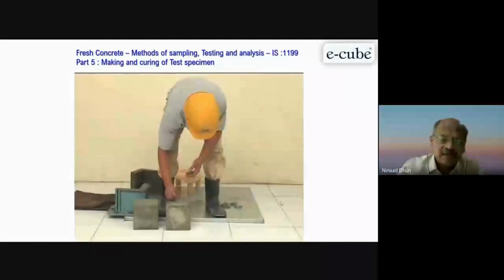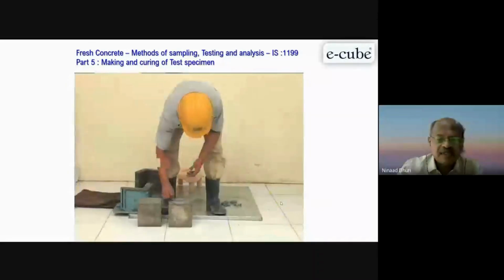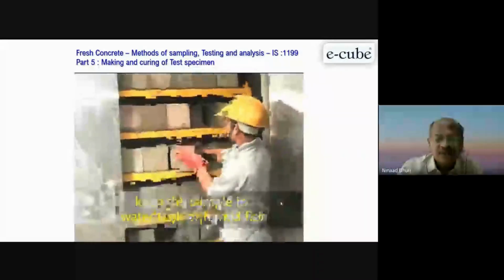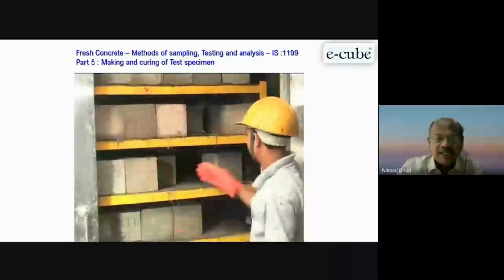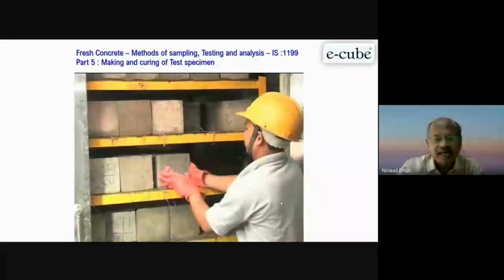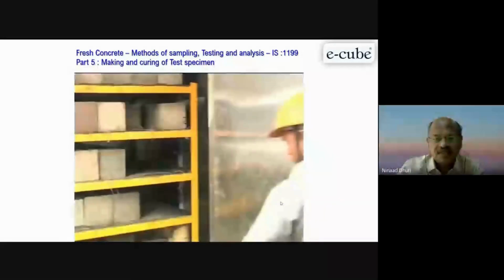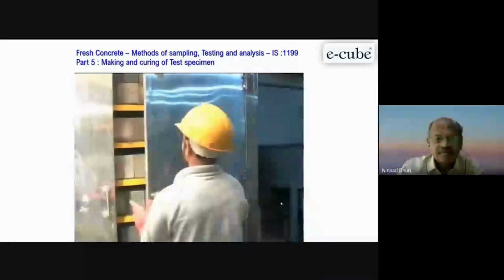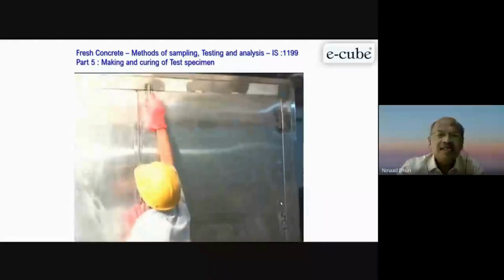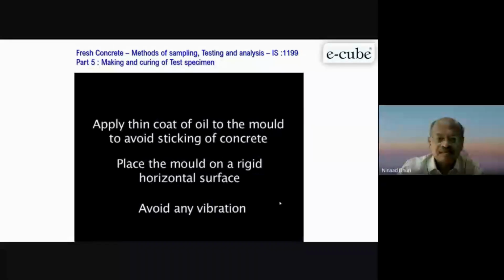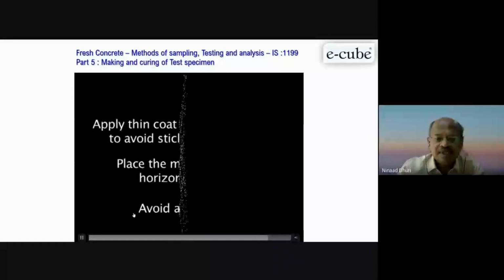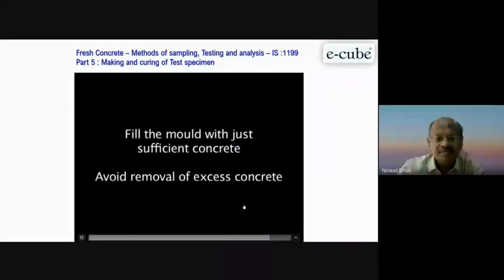Then you can write whatever other identification numbers you want on this, and you can put it into the water, or you can put it in the humidifying chamber like this, where you have around 95% RH, till it is tested. This is very important: no vibration.